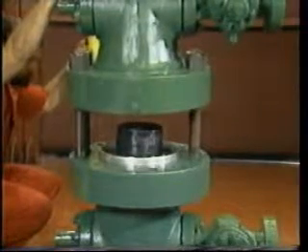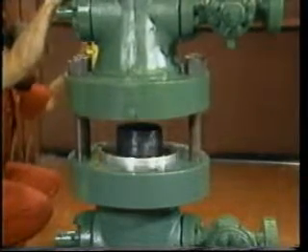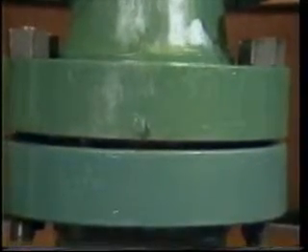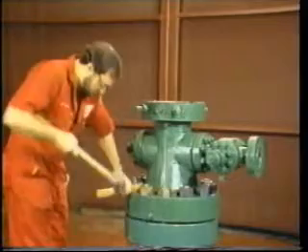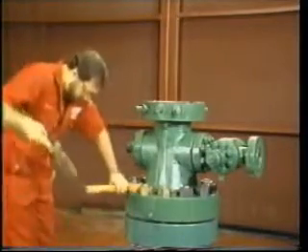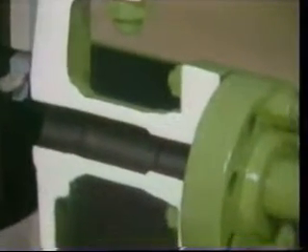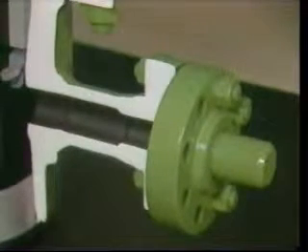The top connection of the casing head may be a clamp hub, or as seen here, a flanged hub. Flanged connections are generally heavier and stronger. Clamped connections offer faster makeup and lighter weight. The casing head should have two side outlets of the same diameter. Depending on the completion design requirements, these outlets may be threaded, flanged, or have a studded flange or clamp hub.